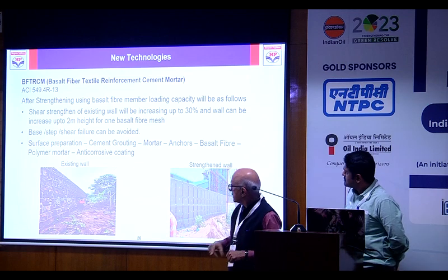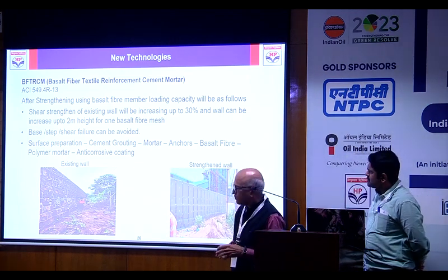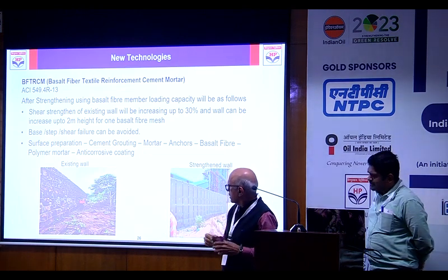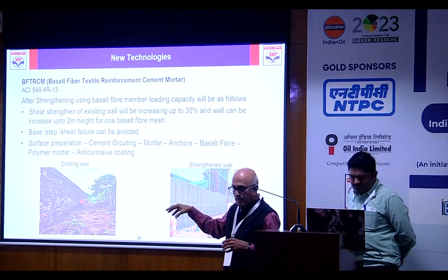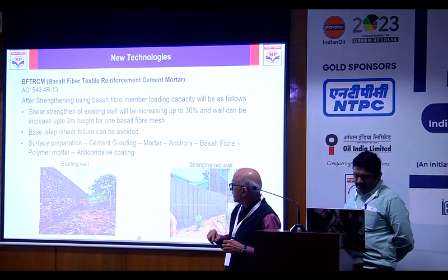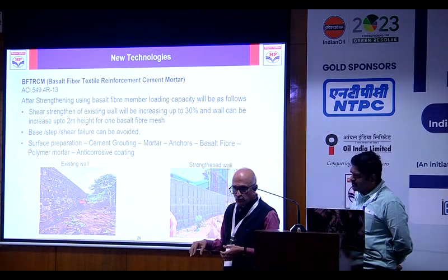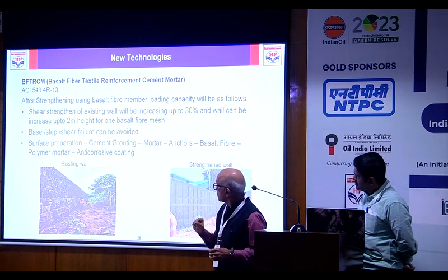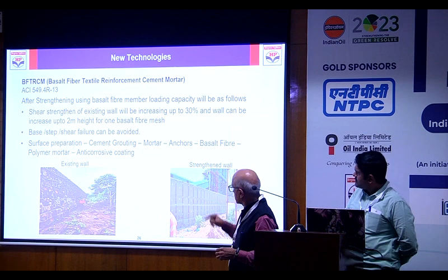Next. Then recently, as per Intelligence Bureau requirement, we had to increase the height of this wall. But this old wall, RCC and stone construction, has a lot of cracks and the carrying capacity was also not there. So the proposal was to dismantle it, take away the stones and put a new wall from the grade. That was costing us around 12 crores. Then this technology came.